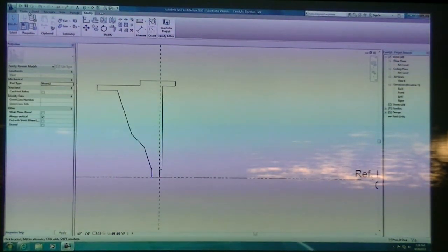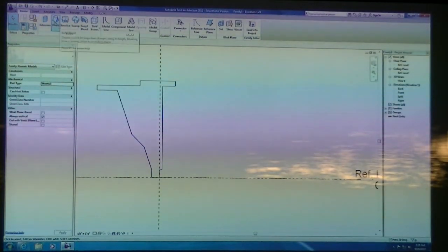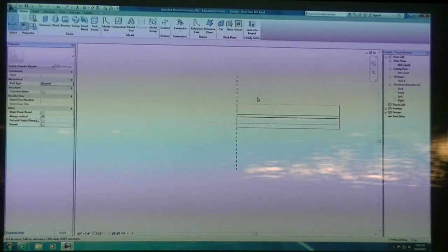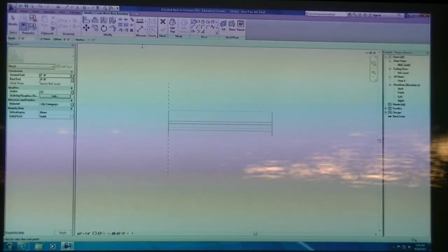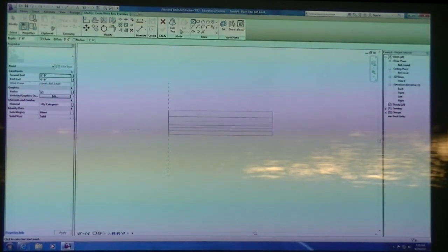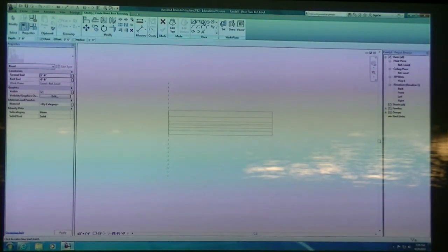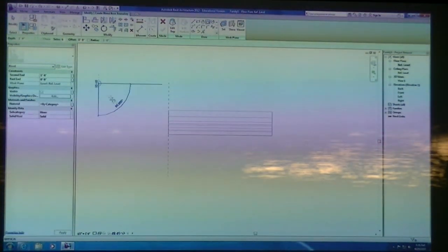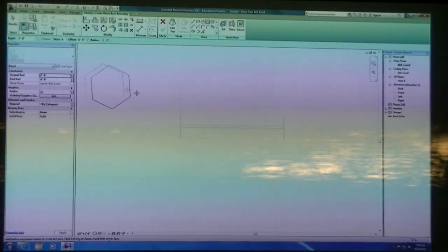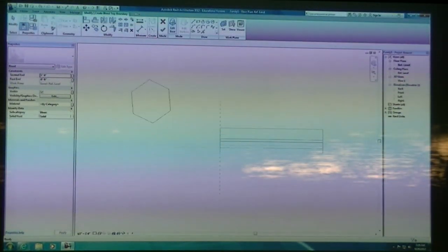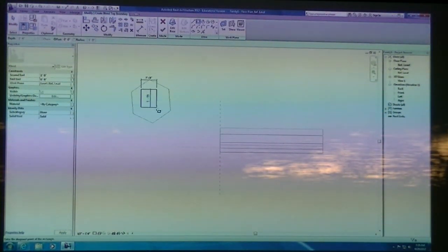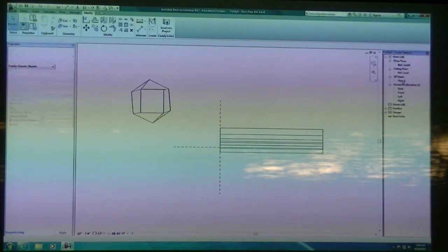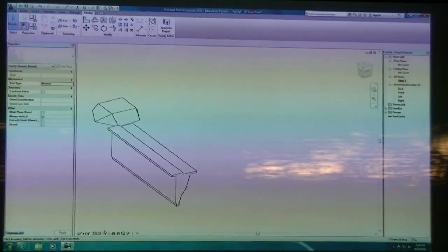So I did the extrusion, we've all kind of done that a little bit. If you do an extrusion blend, that would be something like, if I get into a floor plan view, it has a couple different shapes. It's got an edit top and an edit bottom. So I'll just do one of these circumscribed polygons. And when I click on edit top, I can create the top of what the shape is going to look like and exit out.